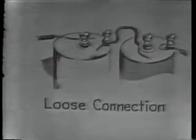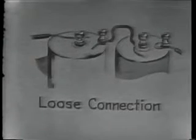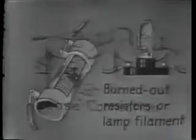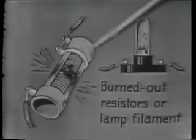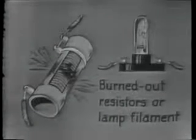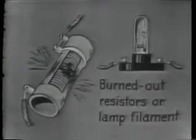Most of the time, a loose connection is the same as no connection, which is the same as an open. Any circuit component with a loose connection opens the circuit and stops current. Another type of trouble that will cause an open is a burned-out component. This is a burned-out resistor. When a resistor gets overheated, its values are changed. But if enough current passes through any resistor, it can be burned completely open like this one.